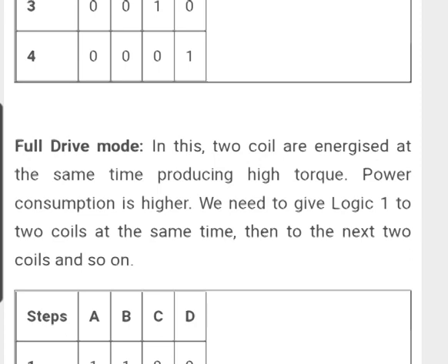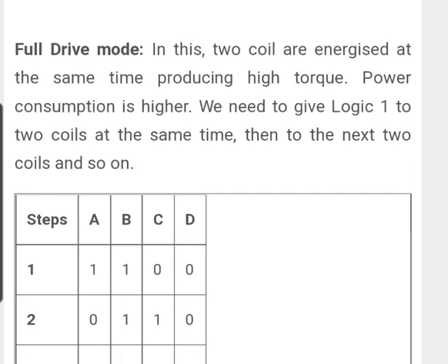In wave drive mode, we have to give a logic 1 to 1 coil at a time, and in full drive we have to give a logic 1 to 2 coils at the same time, then to the next 2 coils and so on.